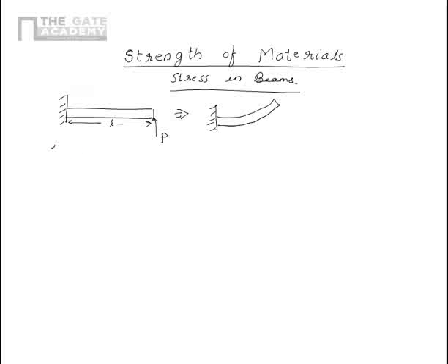assumptions. The first one of them is that the length is far more than the width and the thickness of the beam. That is the first assumption, and it's important. What that tells is that the only dimension of the beam which is going to be affected significantly by the bending moment is the length.